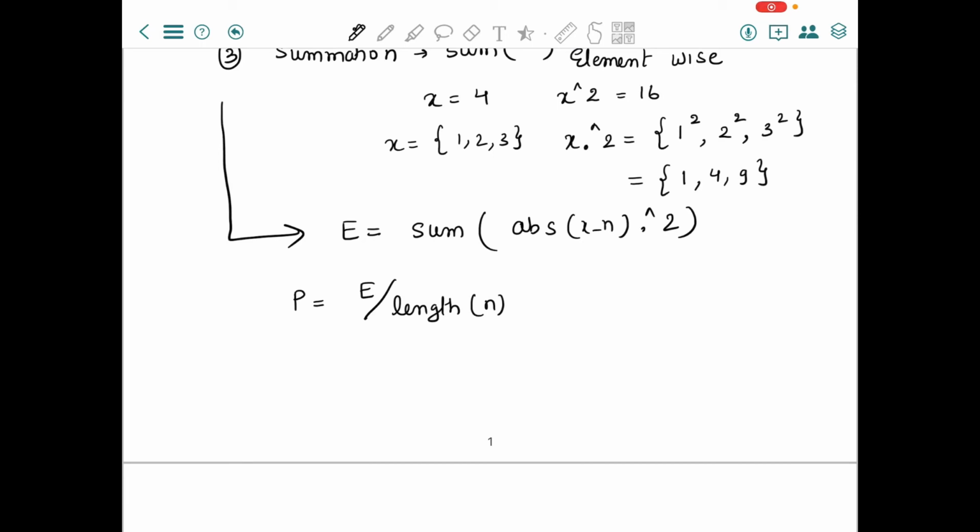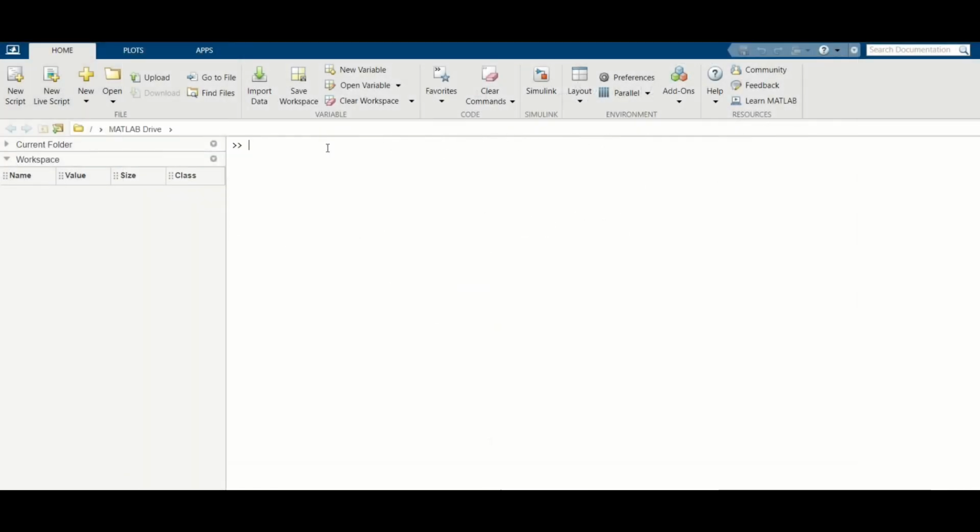Now let's code it in MATLAB, energy and power. As already discussed, we use the function x[n] = n with the interval varying from -2 to 2. So let's take the interval n = -2 to 2, which takes values from -2 to 2 with a time step of one: -2, -1, 0, 1 and 2.